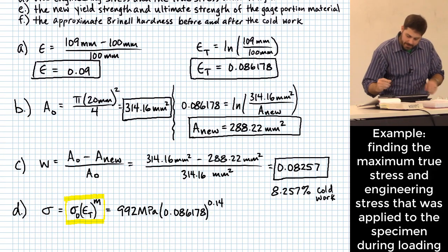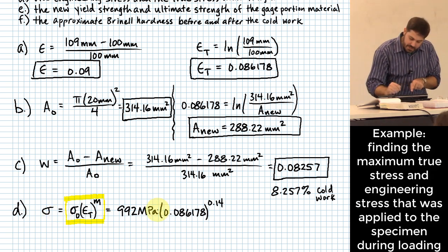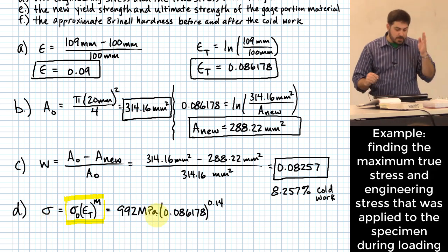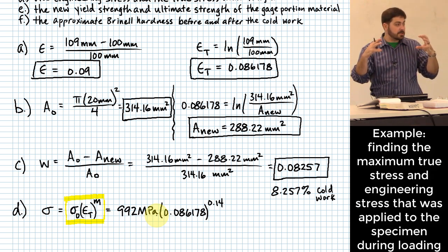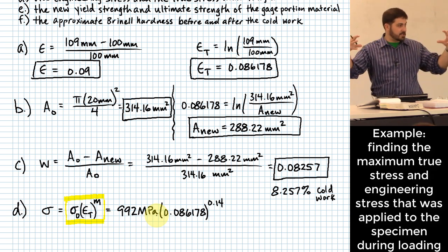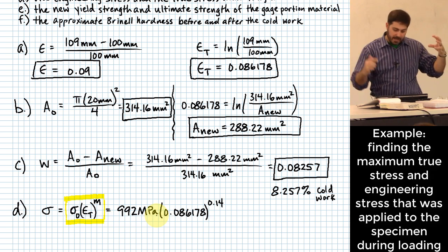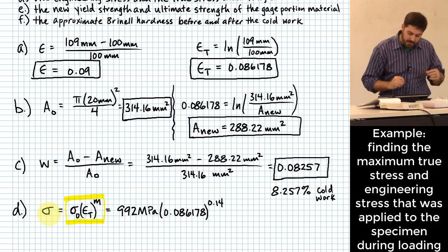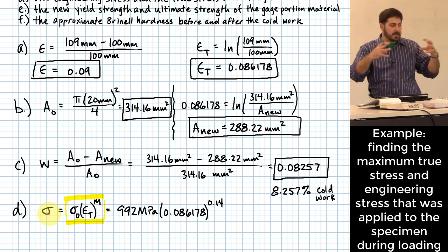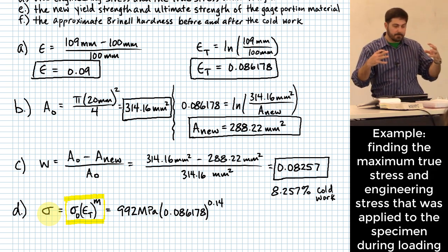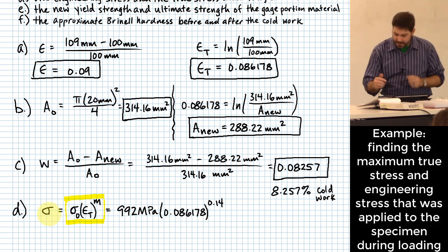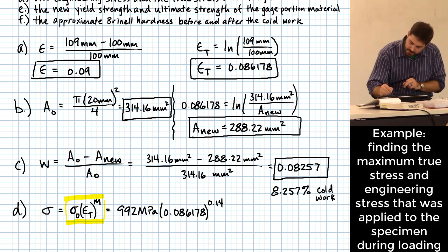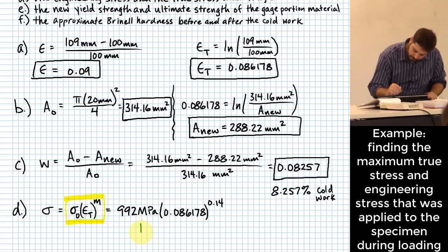So anyway, what we just did there is we found the true strain that existed after we unloaded the material, which is pretty close to the true strain that happened when it was at its full load. And we're going to plug that in here to get the amount of stress that it must have taken to make it get to that point. Does that make sense? Yeah. What table is this? Those two factors were out of table A22.